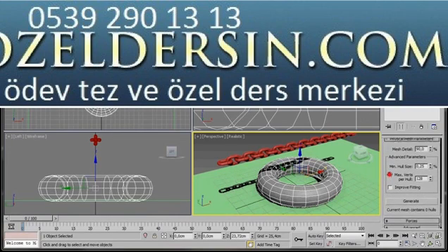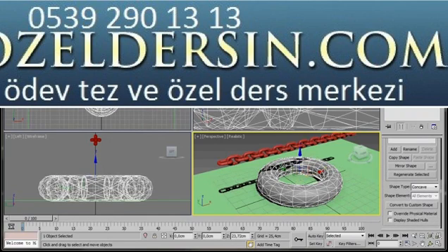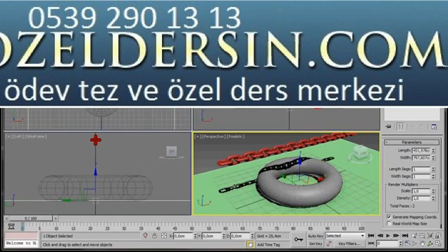This will create a new mesh that will go all around the object. And there we are, that's generated. Notice how it fits right around the object, leaving the center part empty. Before we can start the simulation, we need to apply the modifier now to the plane. So select the plane first, then we'll go up to the toolbar, and we're going to do the same, set selected as static rigid body.